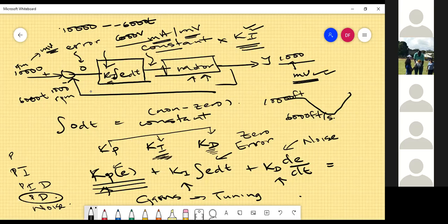All right. So you're going to have to multiply that by a factor that can work with the motor. So that's what the gains in front do. So when this is 6,000, therefore this would have to be like 0.3 or 0.03 times the 6,000 to get a workable or usable value that you can use. You understand? So these modifiers are the ones that calm down, that tell whatever the error is to calm down.